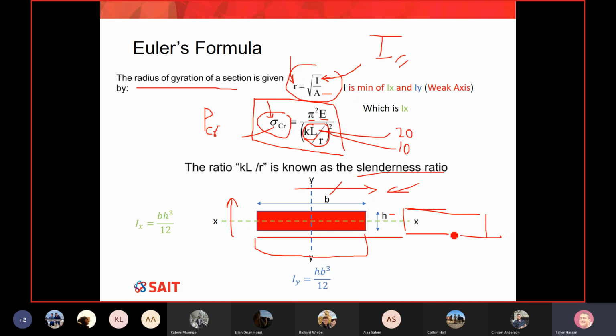Typically, since they play with it, they try to compress it and bend it, and it's way easier to bend on the weak axis. It means it's easier to bend it this way around the x-axis, so after you apply compression, your section will move this way. And it's very difficult to simply move your section about YY. Would you agree or disagree?